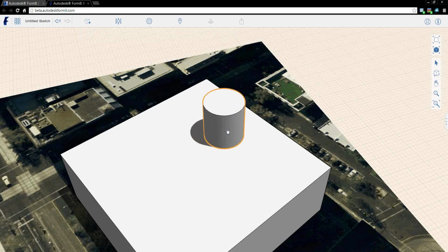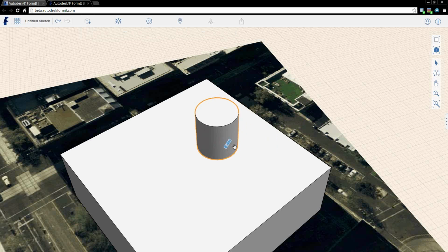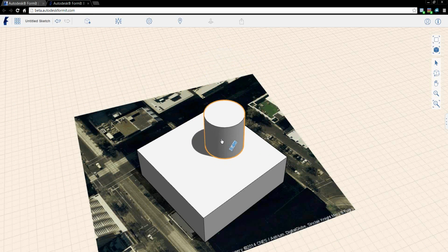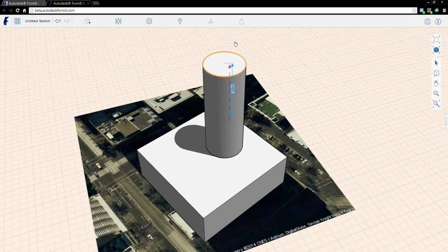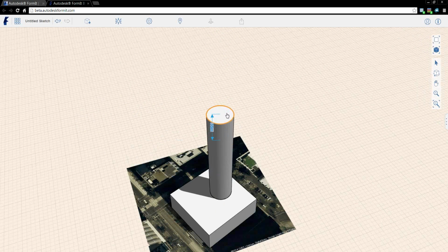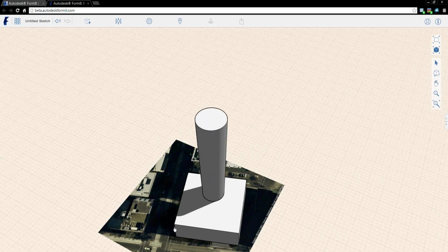in context. So if I start off with the basic cylinder here and just use the zoom wheel on the mouse to start playing with the size of the object, I can double click to get into editing individual surfaces of those objects. And again, we can still use the scale tools to adjust that too. So that was just with zooming in, using the scroll wheel, sorry, on the mouse.